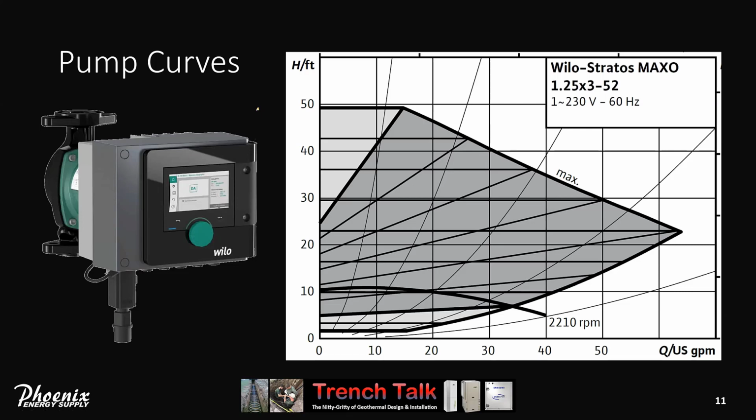So roughly 21 feet of head. So if we apply this in a system where the flow is constantly varying, the pump will automatically change speed to produce a head pressure that keeps it on this control curve.